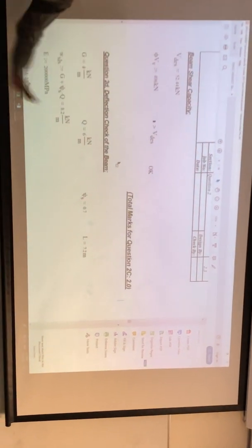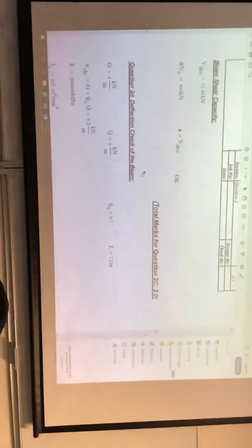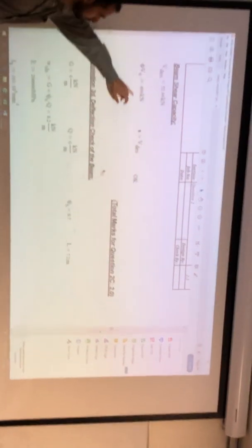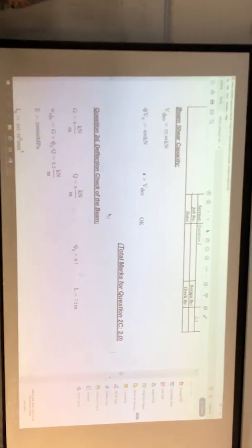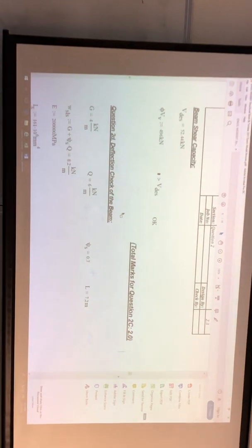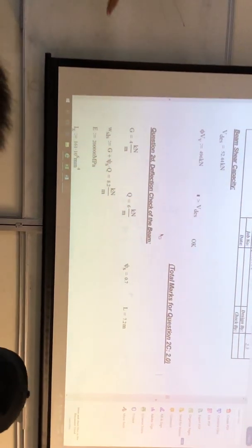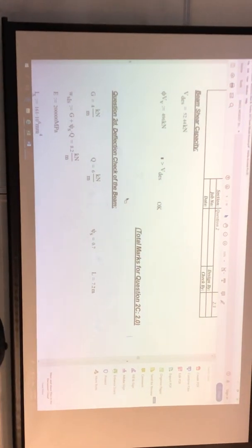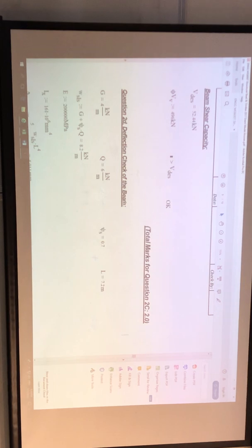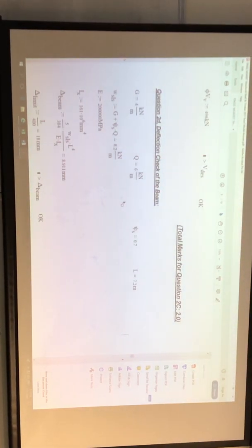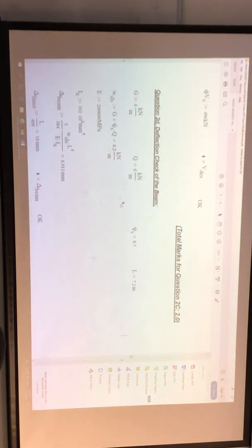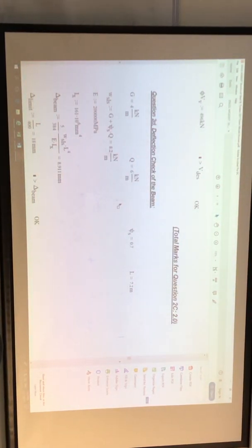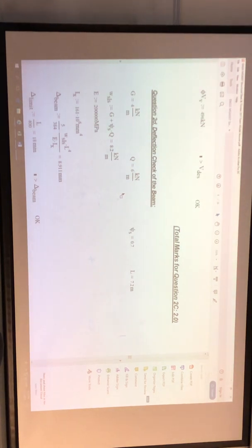As long as your moment is less than 75% of the section capacity, the shear capacity is equal to Vv, right? Otherwise you have to do the ratio, that proportion method, and use the formula to find out. In this case, because it's less than 75% of the section capacity, that's okay. You can just stop there, you don't need to do all that additional formula. A simple check: is your moment more than 75%? Yes, okay, do that check. If not, you just stop there, that's simple.